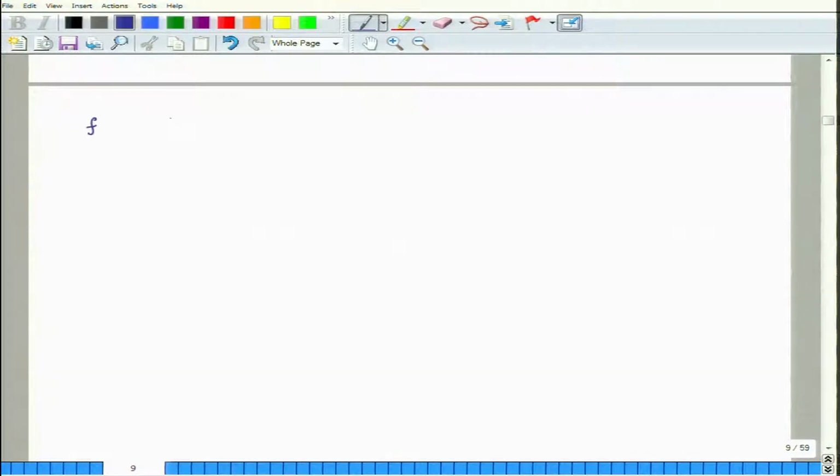So, frequency 125, 250 hertz, 500, 1K, 2000 and 4000 hertz, and the value of LW for this is 103 decibels, 109 decibels, 114 decibels, 117 decibels, 113 decibels and 107 decibels.